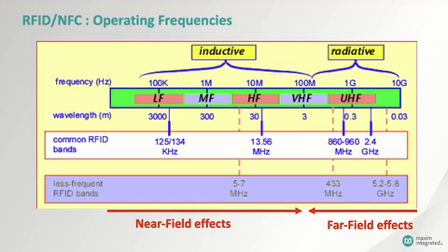But when there is a great distance between the transmitting and receiving antennas relative to the wavelength, the receiving antenna is not directly coupled to the transmitting antenna. Instead, the transmitting antenna is expected to couple the transmitted energy to free space, and the receiving antenna is expected to interface the RF front end of the receiver to free space. Under these circumstances, the receiving antenna is said to be in the far field of the transmitter.